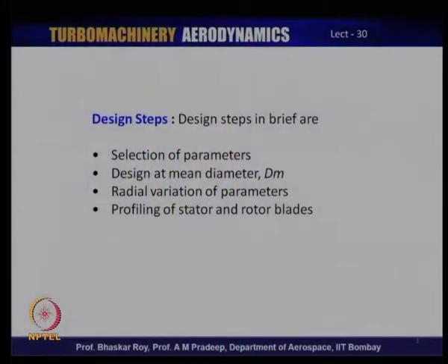Let us get into the fundamental issues of blade design. Now, the first thing that you would see is that you need to select the parameters of design. As we had seen in the last class, the selection involves a number of parameters. Some of the parameters that we had looked at in the last lecture were thermodynamic parameters. They come out of the thermodynamic cycle design of a particular gas turbine engine, and then those thermodynamic parameters become the starting parameters for the axial flow turbine design. Now, those parameters need to be factored in. We will look at them again in the next slide.